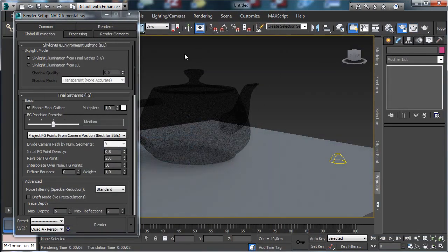Another interesting thing is that we can use the illumination and the calculation done using the unified sampler. The unified sampler gives us the possibility to control and manipulate the parameters for the raytracer in a better way, with both the anti-alias, and to also have the calculation of the motion blur with good quality.